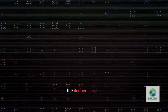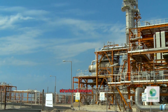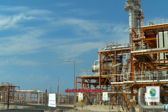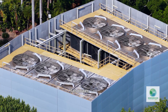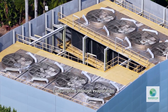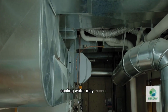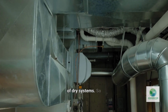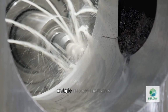And here is the deeper insight. Hydrogen plants in hot desert regions face a structural tension between electricity and water. Dry cooling increases electricity consumption through fan power. Wet cooling increases water consumption through evaporation. In some cases, desalination energy required to supply cooling water may exceed the parasitic fan power of dry systems. So cooling becomes an optimization problem across multiple resource constraints.